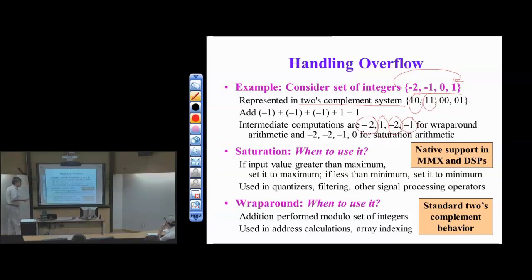Now there's an alternative, which is saturation arithmetic, and this is on your digital signal processor. There are two different add commands. One is add, one is sadd, and the sadd is saturate. I know, I'm sorry, I didn't choose it. So it's saturating add, and there's saturating subtraction. By default, it's two's complement.